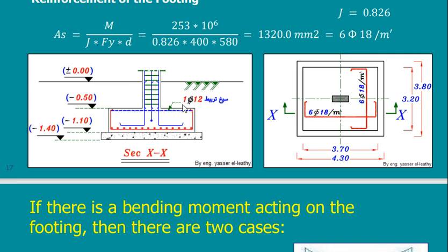This is very important. I don't have top reinforcement in isolated footing. But what about this? What is this dotted line? This dotted line is not a rebar. We call it in Arabic sikh tarbit. It is just a rebar to keep the U-shaped in place, because if I put the U-shaped, they will not stand.